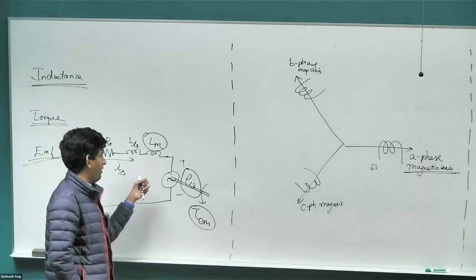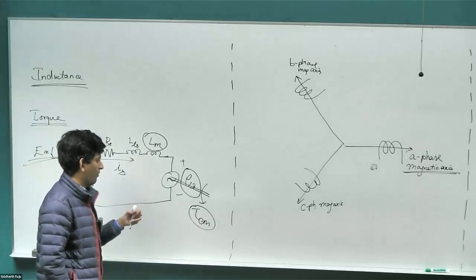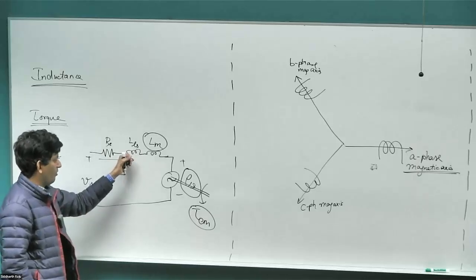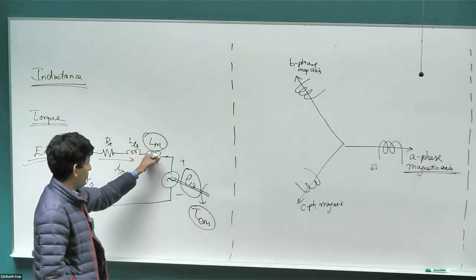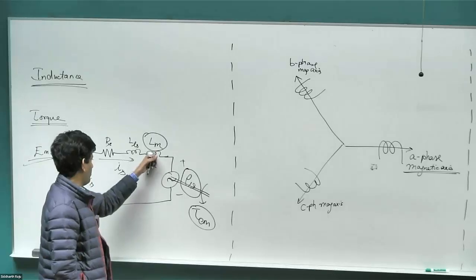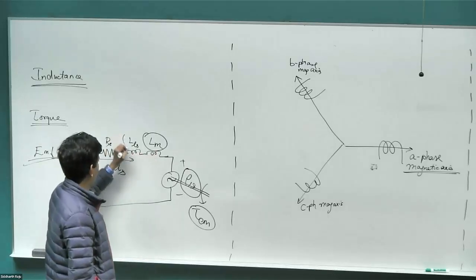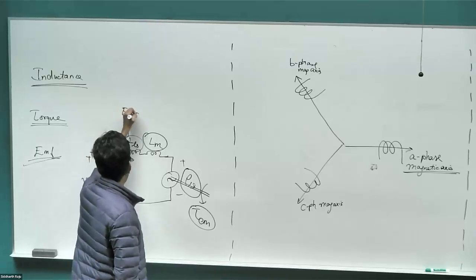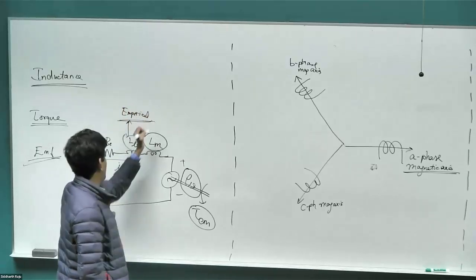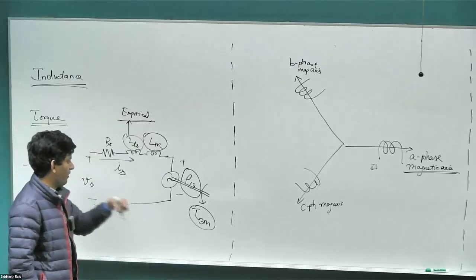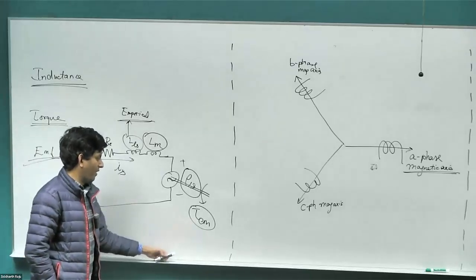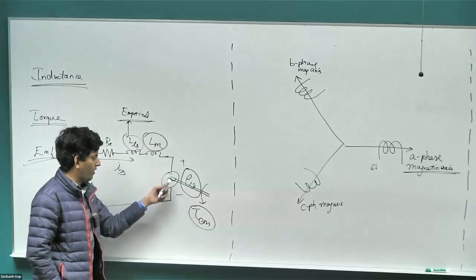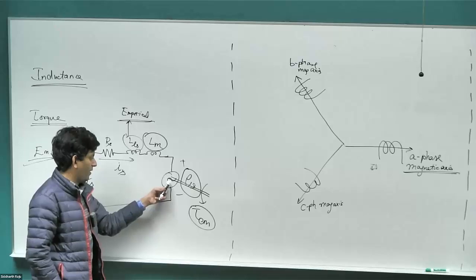Inductance gets a little bit tricky. The inductance that's causing the magnetic field in the air gap that interacts with the rotor. There is another term, leakage inductance, which we haven't introduced just yet. I'll do that once we have derived LM. This term is going to be empirical. I'll explain what it is later, but we are not going to be doing a derivation for it. And then finally, we are going to be deriving the torque expression, and the EMF expression is the same as the torque expression. So I'll leave it as homework for you to rederive it. It's derived in the notes as well, but it's straightforward.